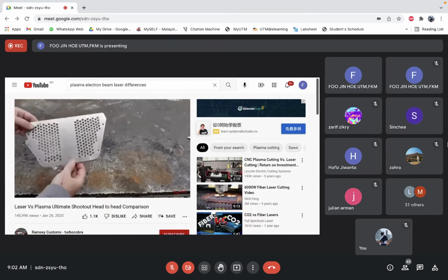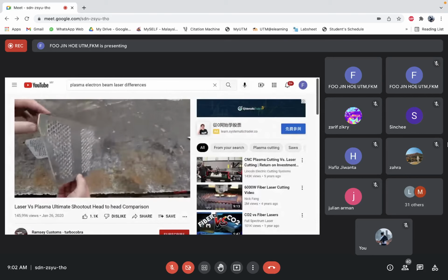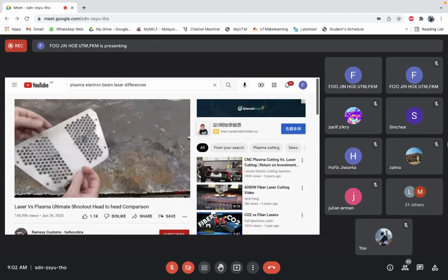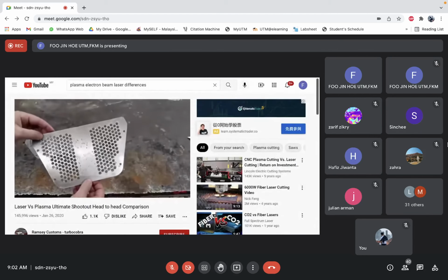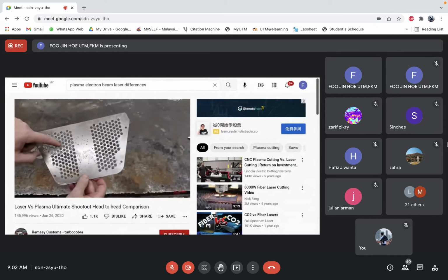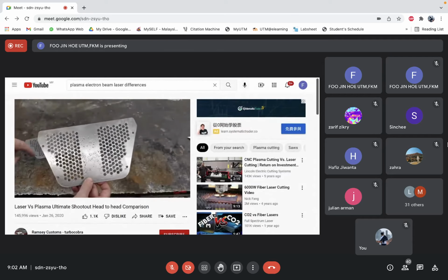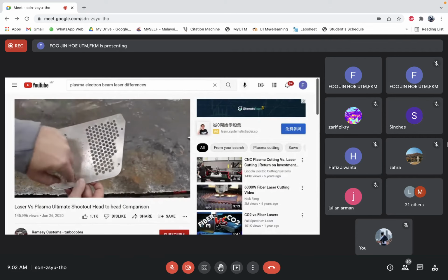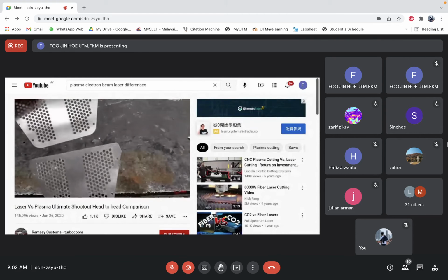Here's the plasma. There's no book specs for this particular combination. Fine cut consumables, 90 thousandths thick aluminum, 3/32. But I have good luck with this setup, 170 inches a minute. Now I will say on the inside cuts and holes, I had those slowed down at 60%, but the outside cut 170 inches a minute. This was 175 inches a minute.